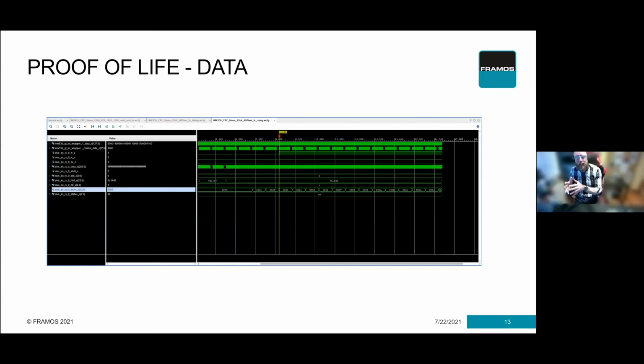So that's a good tool. If you have access to the ISP tuning tools for any particular device, that is by far and away the best way to do it. You follow their recommendations, and those recommendations are typically using a Macbeth chart, using controlled lighting and multiple lighting color temperatures, preferably calibrated. You can then generate an ISP configuration for your particular device.